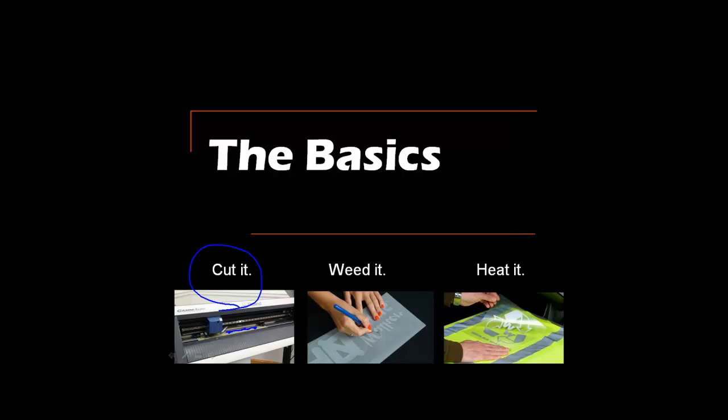Program your artwork, whether it's in Roland CutStudio, CorelDRAW, or Adobe Illustrator. There are some free design programs from Stahls like CADWorks Live. Create your art, send it to the cutter, and it cuts out the design. Now, for CAD-CUT materials, you always want to cut your material in a mirror image, so just simply reverse it in the software before output.